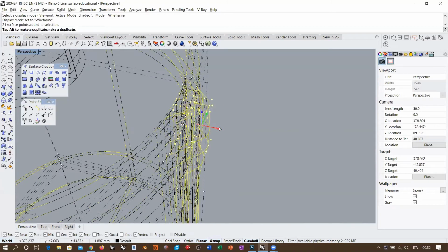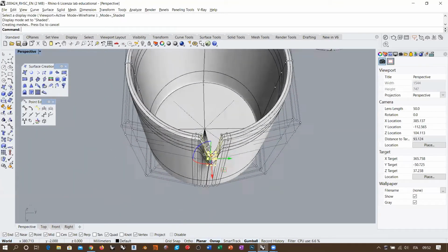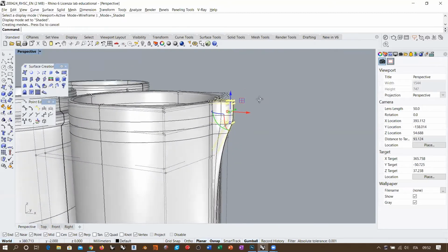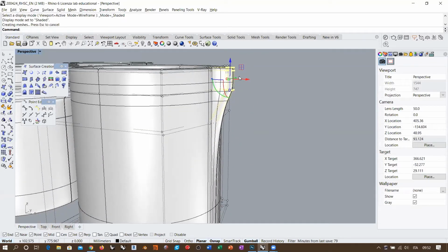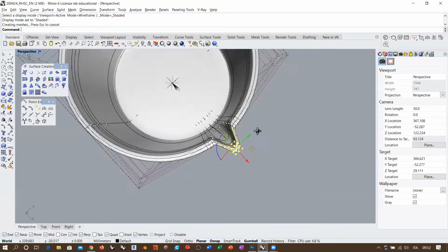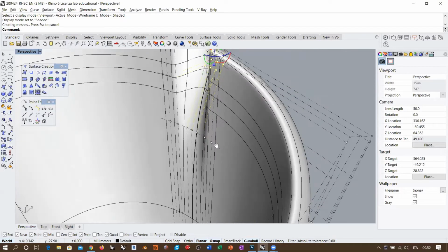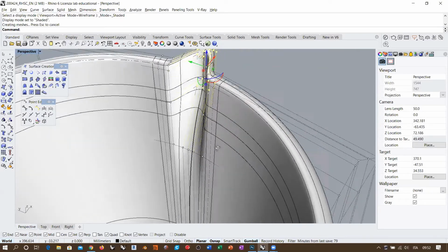So if I do this and move this away, you see I'm not creating any crease along this surface because I'm not breaking the circle rule. But the circle rule is now more local because I have added many knot lines and many control points along the way. Okay, so you see that the internal edge is deforming smoothly because I'm not working on kink points.